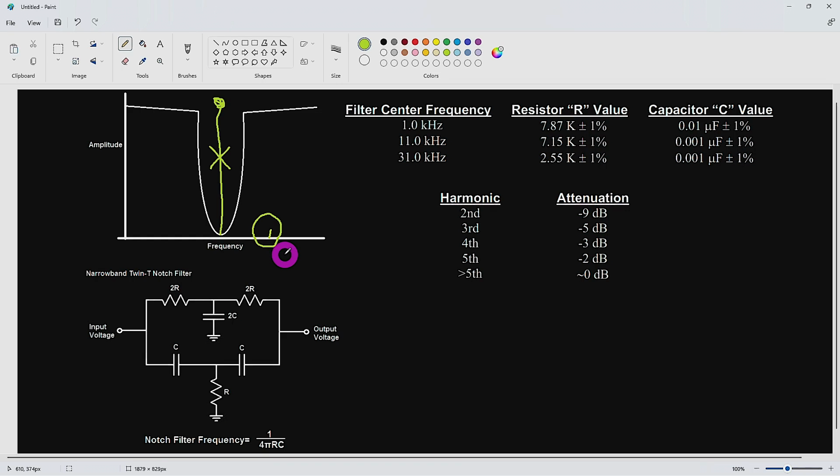It's used all the time to make measurements that go beyond the dynamic range of the instrument if the measurement were to be done in one step. The disadvantage is that, of course, you have to build a filter and the measurement takes more time because it is done in multiple steps. But that's the price to pay if you want to find out what the THD floor is. Now, the instrument's manual already gives you these values very nicely because they anticipate that you will have this problem. And if you want to do performance verification of the unit, this is what they tell you to do.